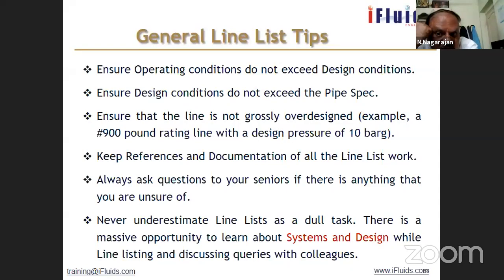There is an important document I told you in one of the presentations, piping material specification, which is prepared by the piping department. That also lists the maximum design pressure and design temperature that can be applied on the particular piping for a particular service. So you have to see that your design conditions do not exceed the piping specification.